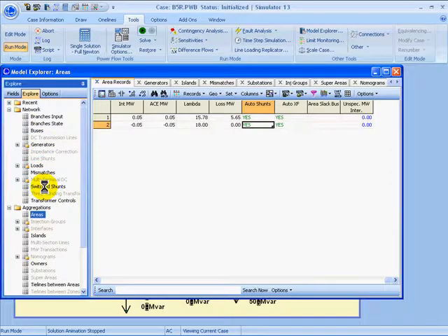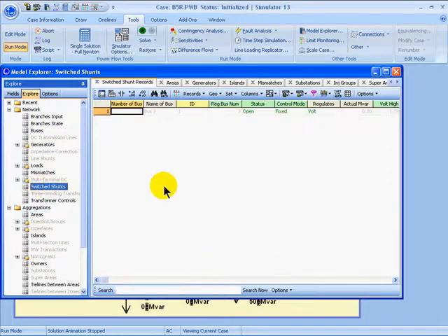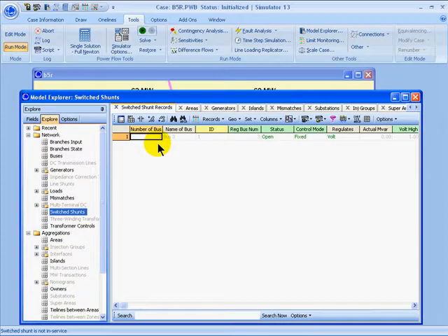So here I can disable its control by placing it on Fixed Control, or by changing its status to Open. I can view or change the control characteristics of this unit by right-clicking on it and then bringing up its dialog.